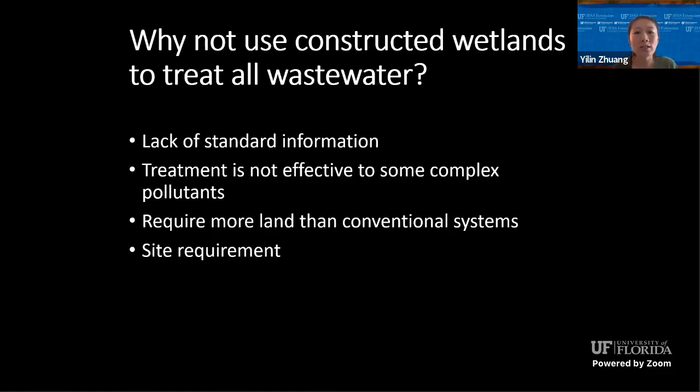In addition, this system also needs more land than conventional systems. High land cost and the lack of suitable land can make construction of large systems impractical. On the other hand, if the site is relatively flat, has deep soil and a low groundwater table, then it is ideal for a constructed wetland.